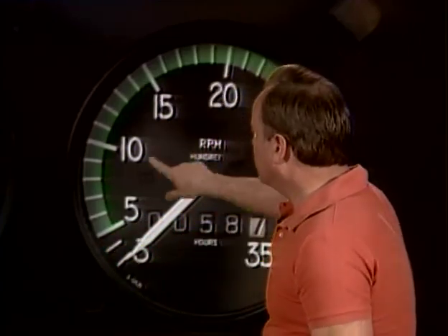Basically, the indicator here is responsive to the frequency, because the synchronous generator, it's actually an AC three-phase generator, is putting out pulses of electricity, and it's the frequency of those pulses that determines exactly how fast the motor turns. So they're basically responsive to frequency. So the synchronous tachometer system is responsive to frequency.